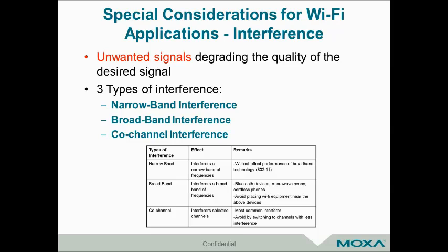So if you have, say, several AGVs that are all going to be clustered in a specific area, you can point that antenna towards that area. It's a sweet spot between an omni and a high gain directional antenna. It allows you to connect groups of devices, but those groups do have to be clustered within the range of that antenna.